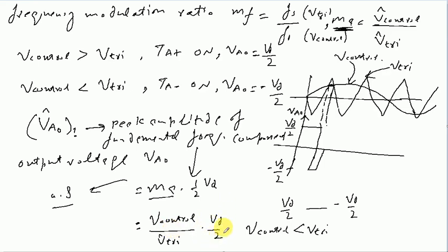For example, we cannot control the input voltage, but it is possible to control either the control or the triangular waveform, and the ratio of these two with the product of the source voltage can help us get the desired value of the output voltage. Now let us see about the other term, that is the frequency of the output signal.